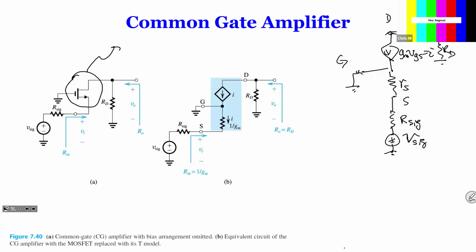Yeah. So, if I go back to the original circuit, often what it looks like, the real circuit will look like this. So the real circuit looks like this at the bottom. So you have drain connected to VDD and source connected to the load and gate is grounded, and you have RL.